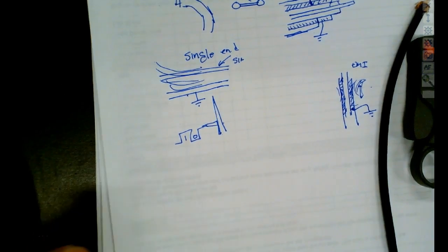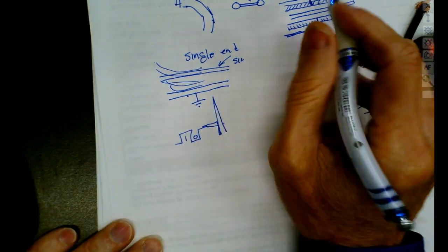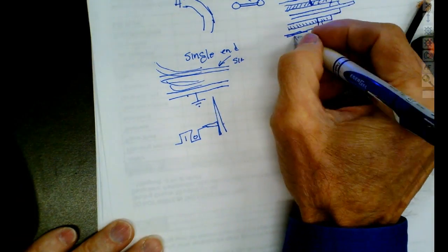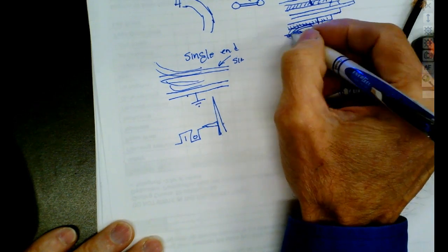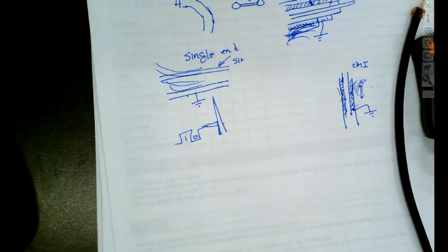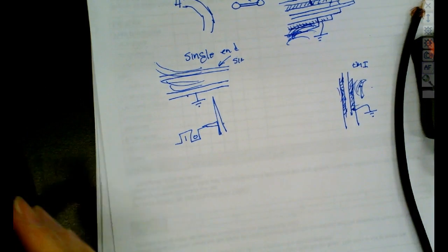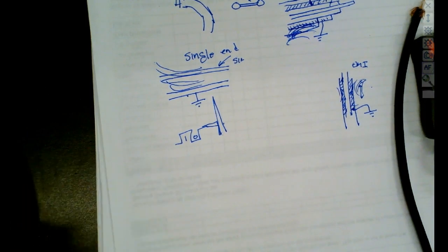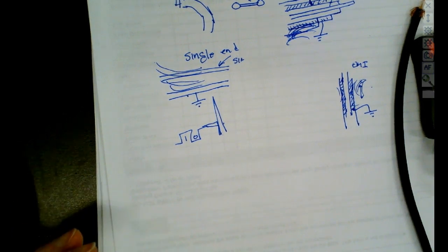So what was going on is that coax cable was really good over distance because the shield was on the outside. So when the EMF came into the shield, it would go to ground and we wouldn't have any problem. But when we tried to use standard wire to send signals, which were inside computers for years, we had to really limit the length of these cables because of...